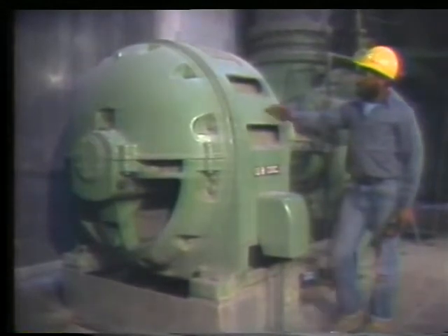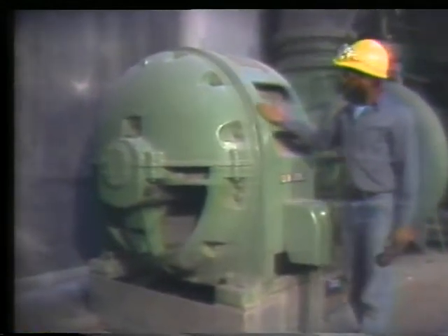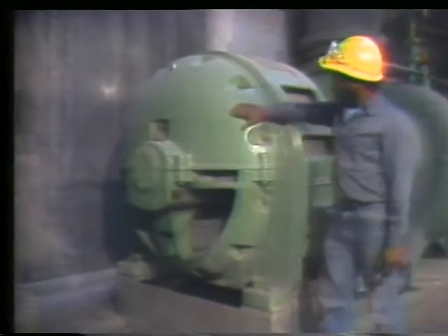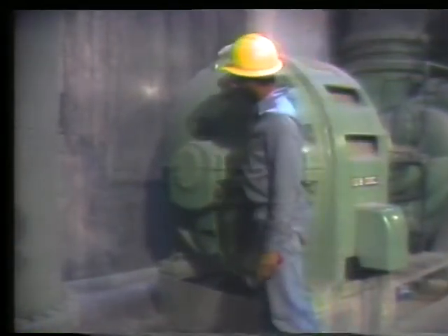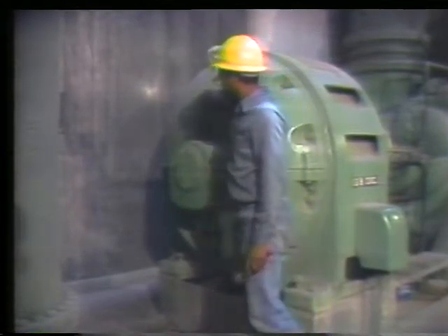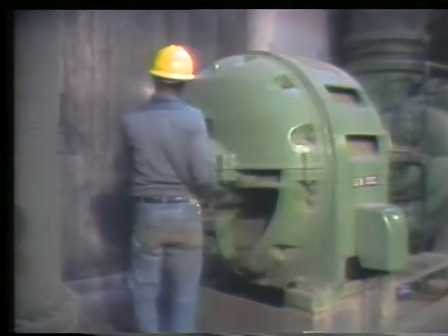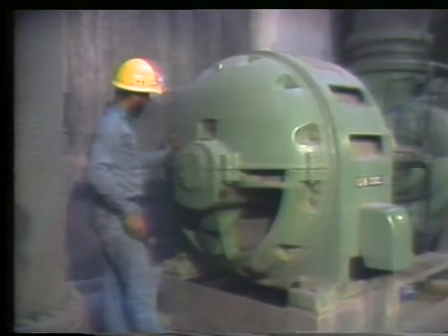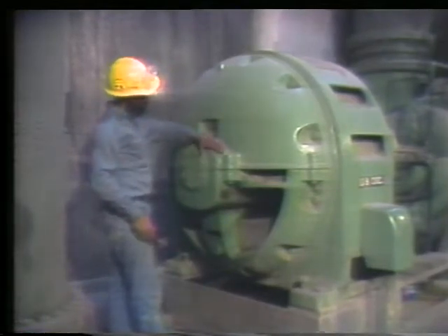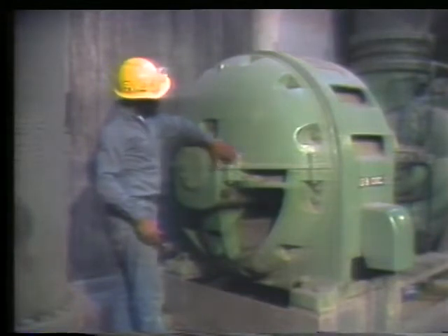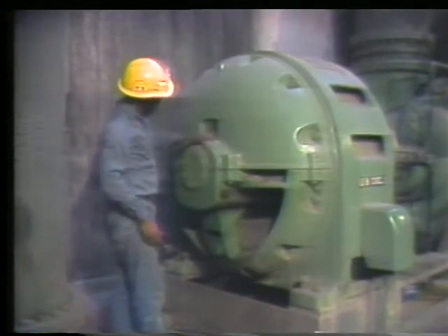Vibration can cause an unusual noise in the motor, so touch the motor. The vibration can be felt as well as heard. By touching it, you may be able to find the greatest area of vibration and thereby locate the problem. But please be extremely careful when touching near the bearings of the motor. If the problem is in this area, excessive heat will be generated there, enough to burn you.